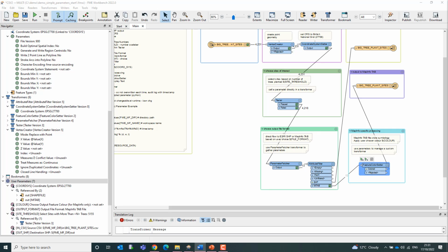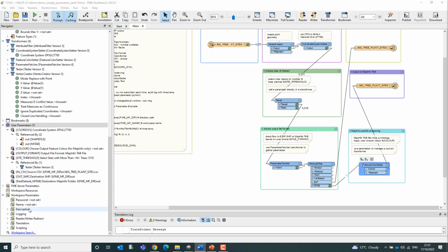Yes, and just a final example really of parameters. I think we've shown you lots of different options. I'm using this time a workspace parameter, so one of the yellow icons down here. Let's use some Python to customize a workspace log file so that each time it's run, the workspace adds a timestamp to the log file name. So this means the log files are stored from each run. They're not getting overwritten, which can be really helpful for auditing and debugging our data processing.